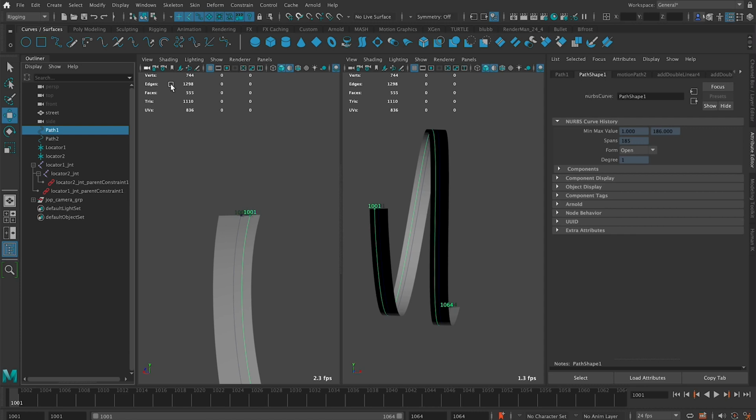And in order to find an up vector from an object, you need 3 points. From those 3 points, you can find the one direction that is perpendicular. If you only have 2 points in a line, every other point around it that is not directly in the path of the line is perpendicular to your line. That's why the flipping occurs, because you can't really calculate an up vector consistently from a curve, which is also why the motion path non-flip option doesn't really work all that well.